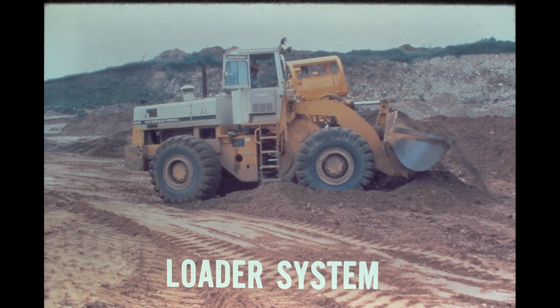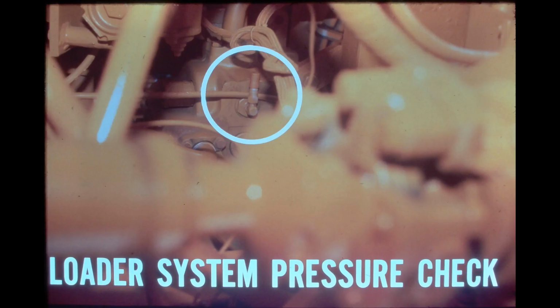If the steering is normal and the loader is slow at all speeds, a loader system pressure check should be made. A quick disconnect is provided on the bottom of the loader control valve to check the loader system pressure. Use a gauge with a hose long enough so you can stand away from the machine. Raise the boom to maximum height and read the pressure on the gauge first with the engine at low idle and then with the engine at high idle.